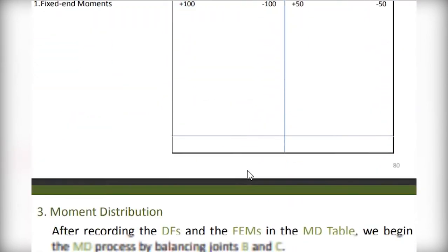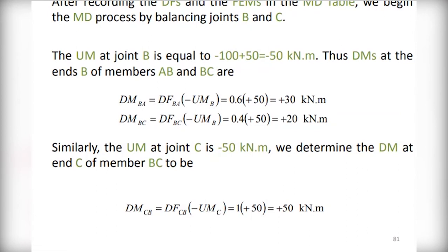After having it, create the table. As we said, take this one, you add the values, and you have the negative. Now this one should be multiplied by negative 1. So the unbalanced negative times the distribution factor gives you this value, because this one times this one. The same here, this one times this one, you get this one. And this one should have the unbalanced one.